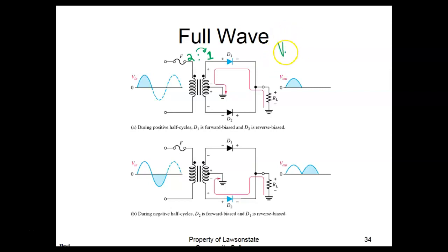So V out of the transformer, and these are AC, by the way. I'm going to call it V_T for transformer out, would be equal to Vn times the ratio, out over in, so times 1/2. That's how easy it is. And of course, if it was the other way, if it was 2-to-1, it's going to be out over in, but that's 2 over 1. So V out of the transformer would be equal to Vn times 2. So that's all you have to do.